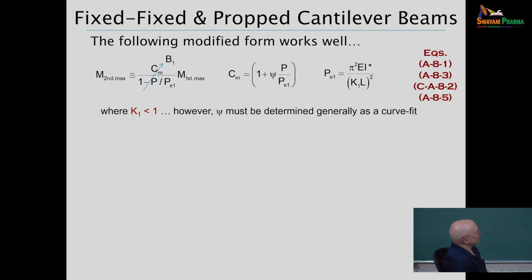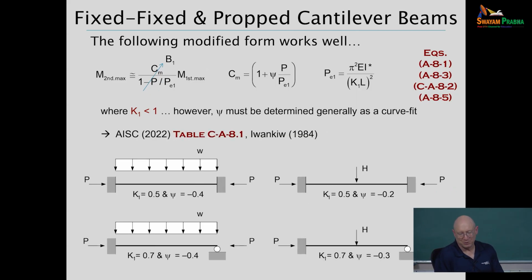So for other cases, we can use this same form, but here we essentially have to revert to the rigorous calculation from the theory of elastic stability, and then say, what psi value do we need in order to fit the results of the theory of elastic stability solution?